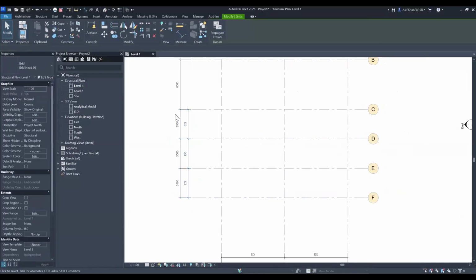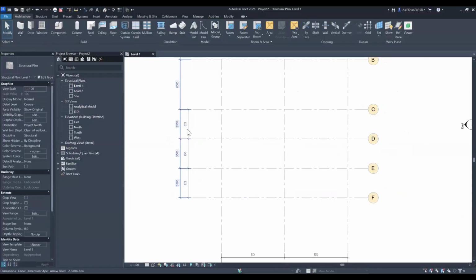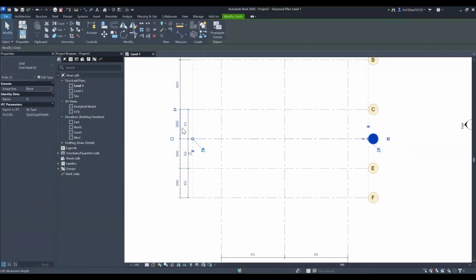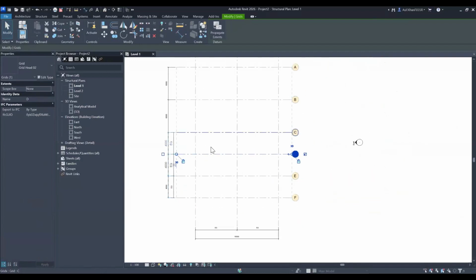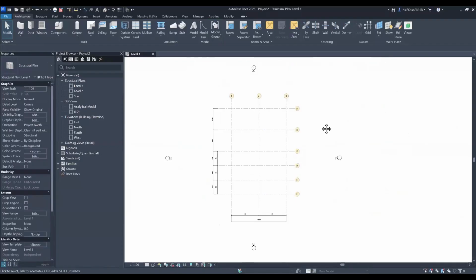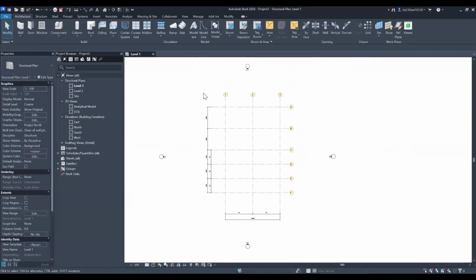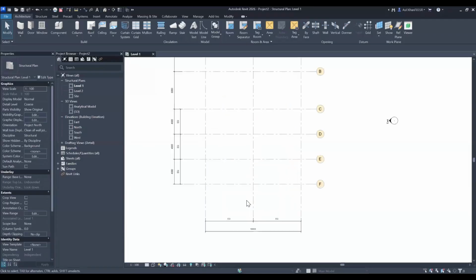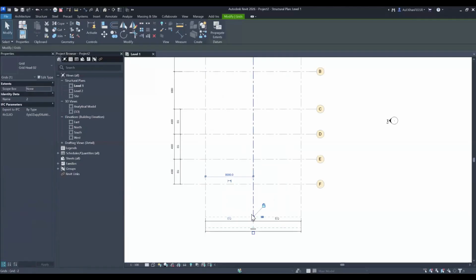Now selecting one of the grids, such as I want this spacing between C and D, let's say 4 meter. Just press 4 meter, everything is spaced out 4 meter. Now, as you can see, within just a few minutes, probably I have spent 2 to 3 minutes to do my grid setup. Now, imagine if I have to do this in AutoCAD, all those things I have already talked about, layering, line, then assigning, many different works. That's too much work for me.